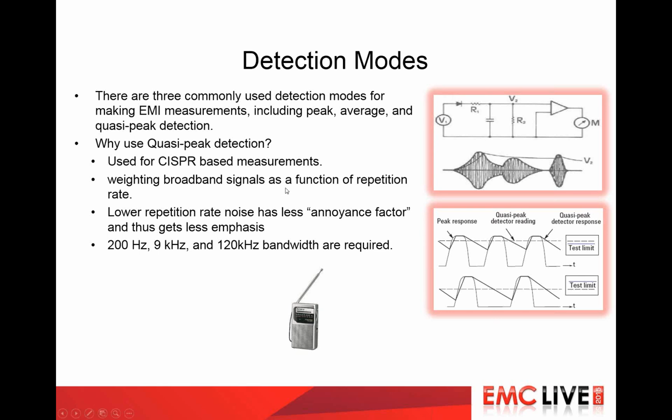So if you have something that sends out a spike periodically, even though it may go above the threshold, if it doesn't stay there long enough to charge up the capacitor, it may not be an RF spike that you have to chase down and get rid of.